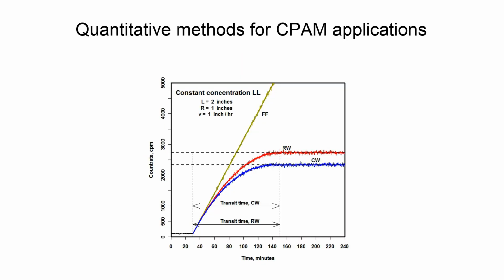As discussed in the referenced paper, there are at least 11 possible quantitative methods for estimating the concentration or quantities derived from it. The concentration may only be at a specific time, or it might be an average over some time interval. This averaging is perfectly acceptable in some applications. In a few cases, the time-dependent concentration itself can be estimated. These various methods involve the count rate, the time derivative of the count rate, the time integral of the count rate, and various combinations of these. The count rate is, as mentioned above, developed from the raw detector pulses by either an analog or digital rate meter.